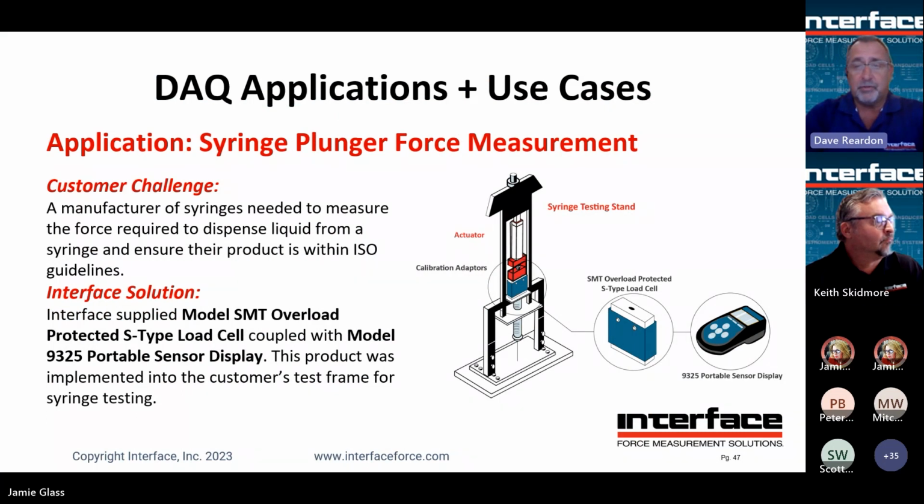The customer was looking for a method to measure how much force is required to dispense liquid from a syringe, a medical device, obviously. So we supplied them with one of our SMT S-type load cells, coupled with our Model 9325 portable sensor display. It's a handheld device.